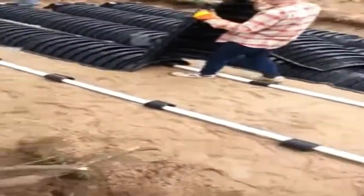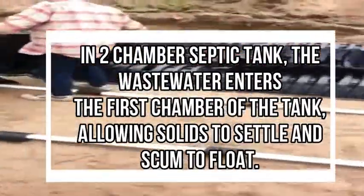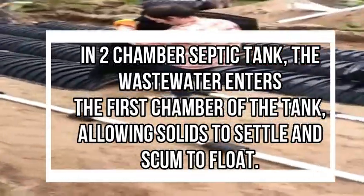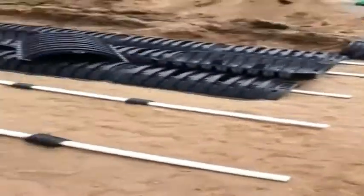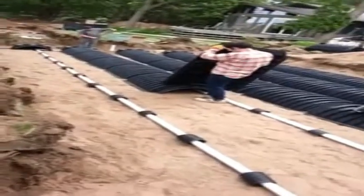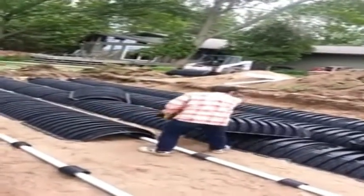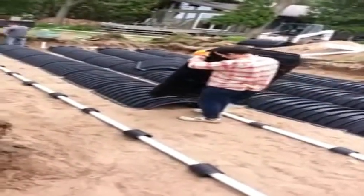In a 2-chamber septic tank, the wastewater enters the first chamber of the tank, allowing solids to settle and scum to float. The settled solids are anaerobically digested, reducing the volume of solids. The liquid component flows through the dividing wall into the second chamber, where further settlement takes place.